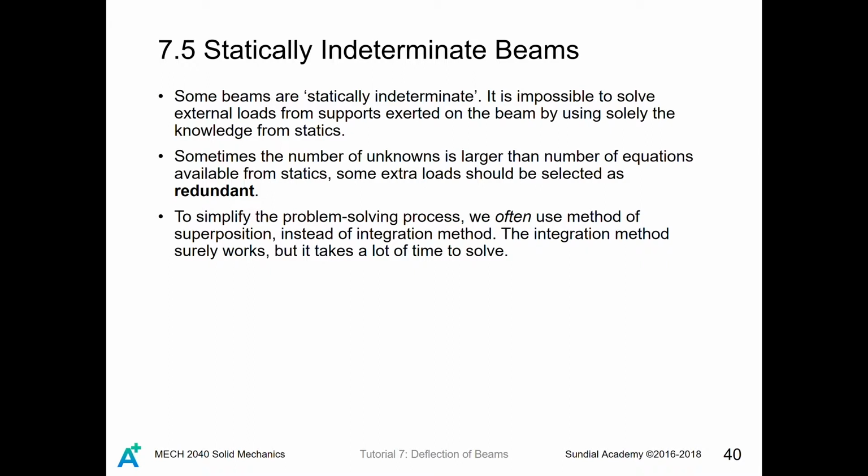Sometimes the number of unknowns is larger than the number of equations, as I mentioned. So some of those extra loads will be selected as redundant. That is, we temporarily select some loads as redundant, something we pretend that we know, and we can simplify the problem-solving process. So we often use the method of superposition instead of the integration method, because although it really works, it takes a lot of time to solve.